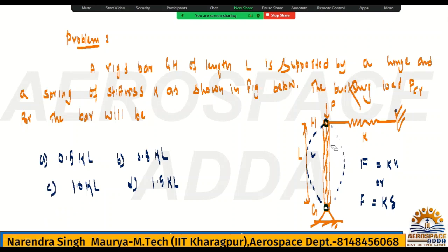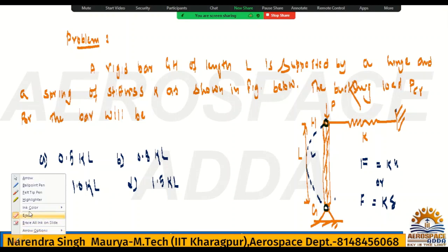Both sides you can take the deflection. This side we have the spring. If you show deflection this side, then the spring will be compressing, meaning that if compression comes, the spring will shorten in length, so the deflection will be negative. And if the column deflects this side, then the spring will elongate, and you will consider that deflection or deformation positive. That's the only difference.